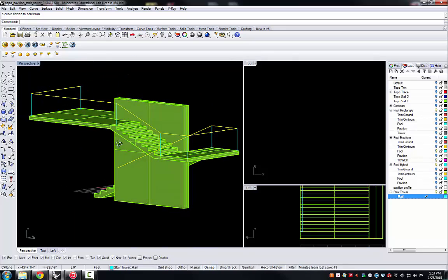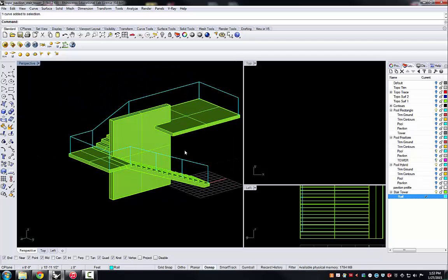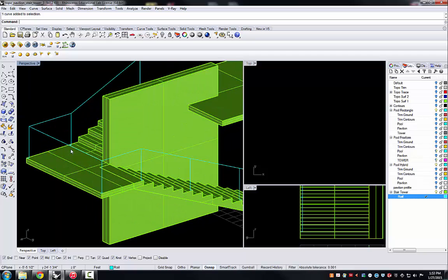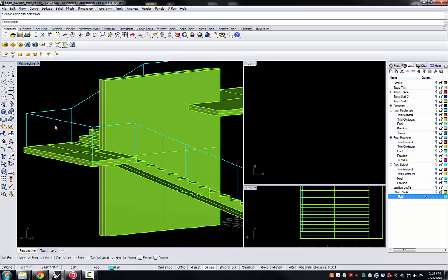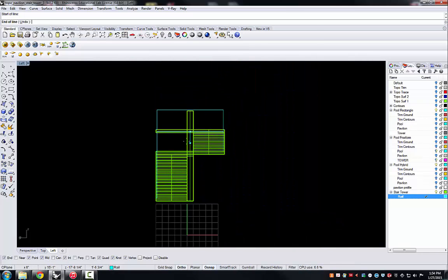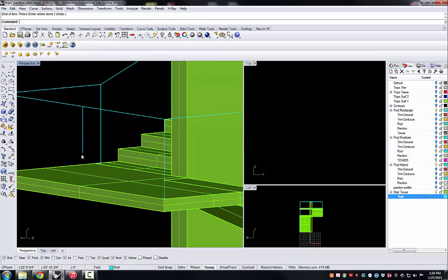I want more vertical subdivisions in order to hold this up in a more believable way, kind of like we have on the near end of the stair. And so I'm going to start placing some vertical lines at various points, line segments from the midpoint, let's say, of this end. I want it to go straight down, so I'll work in a view like the left-hand view, and I'll hold Shift, and I'll only put it part way down. So when we go back to perspective, you'll see that I made a portion of this.